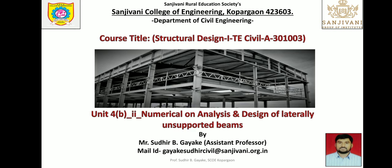We are dealing with unit number 4, that is the design of flexural members, and in the previous video we have seen introduction to laterally unsupported type of beams. That is when no lateral restraint is provided to the compression flange of your flexural member or I section, and this particular I section is subjected to torsional buckling along the length of the beam. In that case, these beams are categorized under laterally unsupported type of beams.